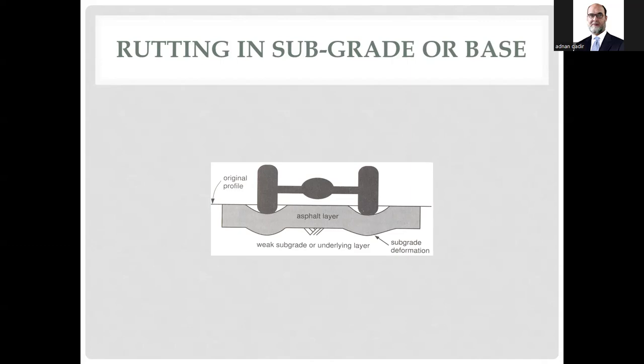And then we have to know why this subgrade failure has happened. Maybe there is a water line passing, and that may have created some moisture, and because of that moisture the subgrade has weakened. Or sometimes we do digging and trenching while laying service lines before road construction, and we have not properly compacted. Anyhow, this is a disaster.